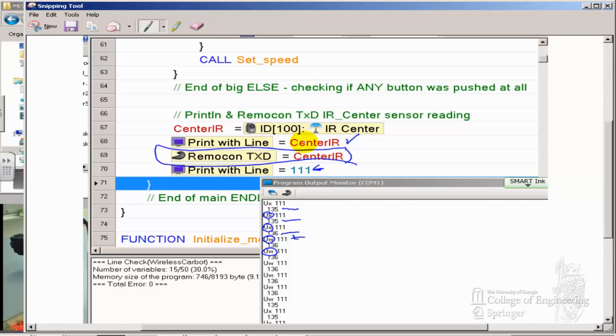So when you do a print line and the number, it prints out that number in the RS-232 protocol. That means what? It actually sends the characters 1, 3, and 5 for the number 135. It sends that character in the clear in RS-232, because this output monitor here is all designed for that. It's like, hey, that's what I got. All it does is pick up a bunch of 0s and 1s, expecting a certain format, and then print it in a certain format. So therefore, everybody matched. The bot sends the proper format, the PC expects the proper format, everybody's happy. They print out the proper things.